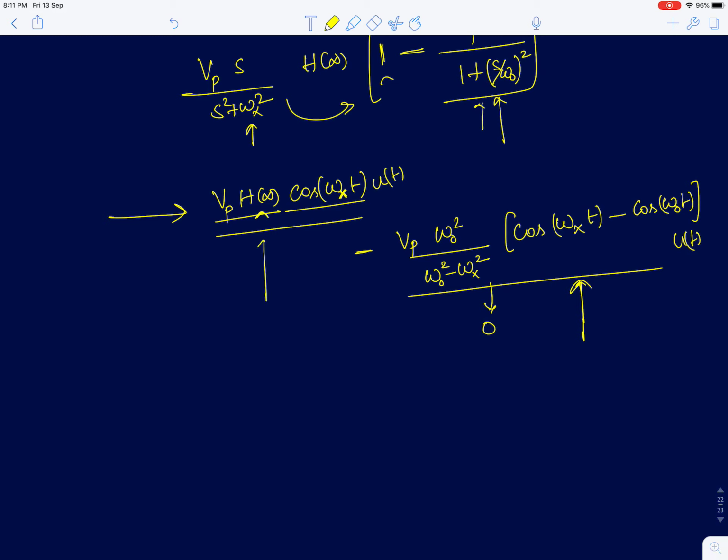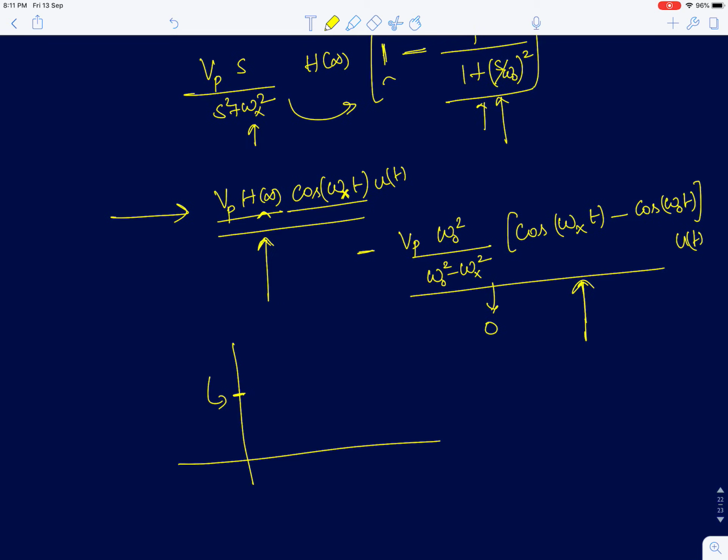On the other hand, for a high pass second order lossless system, you are going to get a sine wave immediately. I mean, you are going to get a replicated version of the input sine wave immediately at t equal to 0. After that, the waveform will look different. But at t equal to 0 and in the vicinity of t equal to 0, the input will just be multiplied by h infinity. And that comes because of the high pass nature of the system. When I say the high pass nature of the system, all it means is that the output can actually have sudden changes.